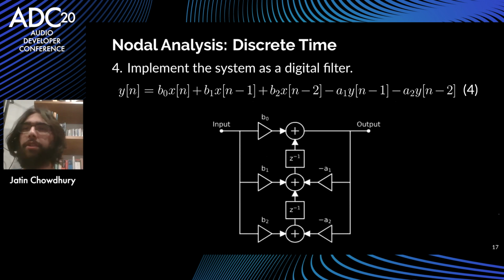And then once you have your transfer function in the z plane, we should be able to implement it with some digital filter, which is something like what you'll see here, where you've got some delay units, some additions, and some multiplies. Between those three things, we should be able to implement any linear digital system that you would describe with a transfer function like that.